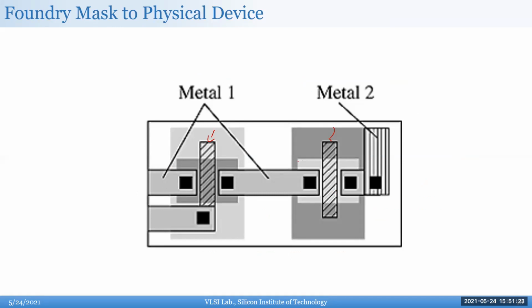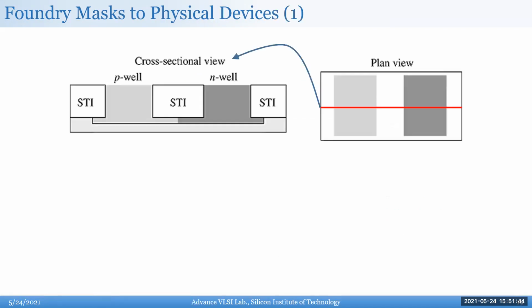Okay, so I'll show the STI process steps again. As I showed before, this is an example of just an NMOS and PMOS connected. Their sources are connected, drain connected to maybe VDD and so on. And you draw this layout. And for each of these masks, hopefully now it makes more sense how it steps. When I first showed you, I just said, just imagine this is converted to this step here. So here you can see how they use the mask to take that layout and convert it into the physical layer.